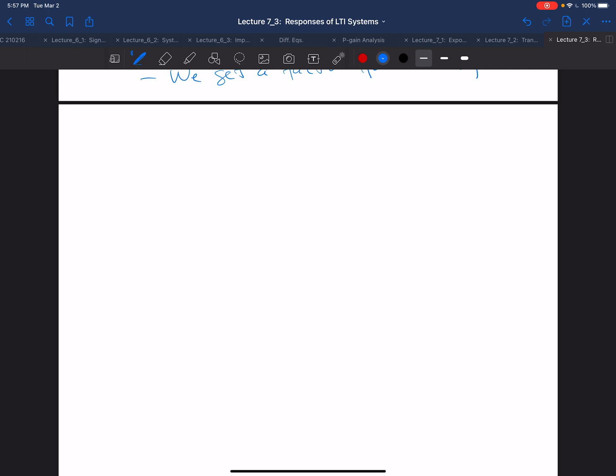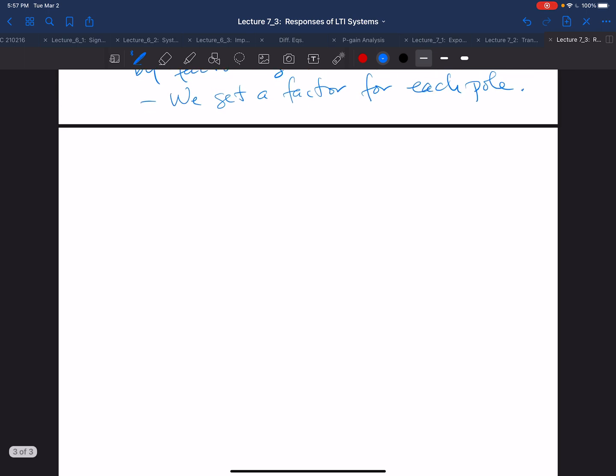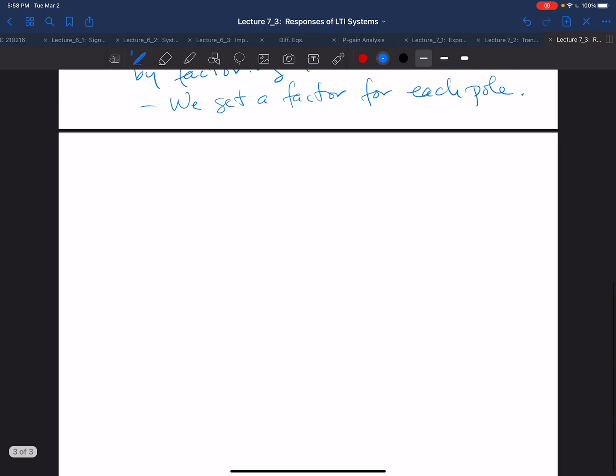I would say there's a particular reason why we're really interested in the effects of poles, and we'll see an illustration of that shortly. The fact is that when you're designing control systems for a given system, you can, in a sense, shift its poles around. And so we're in particular going to be studying the relationship between the positions of the poles of the transfer function on the complex plane and the behavior of the system, the form of its responses. So let's look at an example.